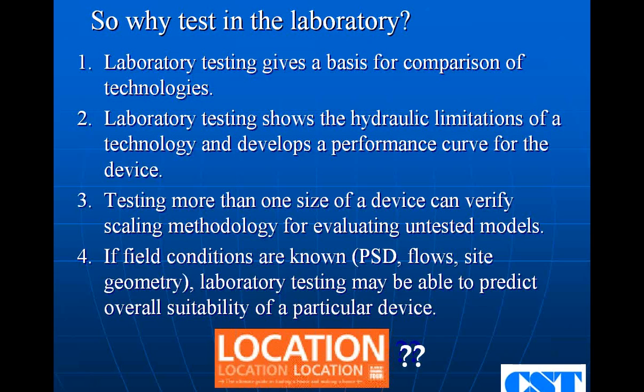The one I talked about in Griffin would never have been put in the ground if somebody had figured out that the weirs in it would not work as conceived. There was a major manufacturer that had to lower the bypass speed on all of his devices, the published speed, because he'd never taken it to a lab. He had calculated a circular orifice pushing so much water to a manhole on the side, but it turned out circular orifices that size don't work very well when you look at Manning's equation. And there were some other things, some flow restrictions that hurt him.